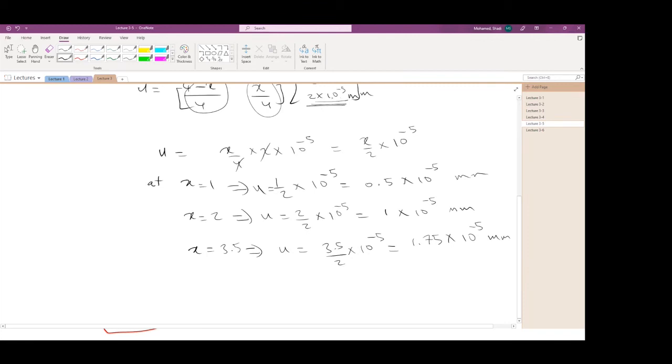And think about it, if you have the shape functions with a unit, then you have the shape function to be a unit of meter, multiplied by the displacement, in this case going to be in millimeters. So the resulting displacement is going to be meters times millimeters, which is not a unit for displacement. This is a unit of area. Now, usually the unit for area, you have it in square millimeters or square meters.